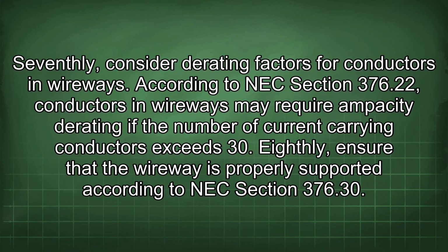Seventhly, consider derating factors for conductors and wireways. According to NEC section 376.22, conductors and wireways may require ampacity derating if the number of current carrying conductors exceeds 30.